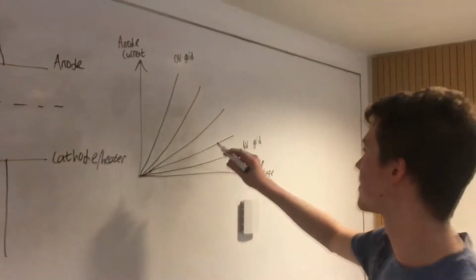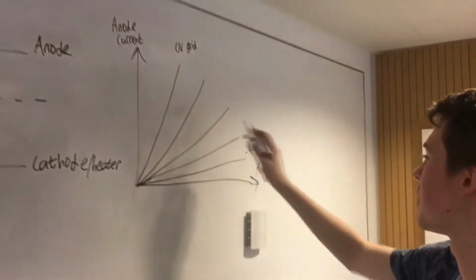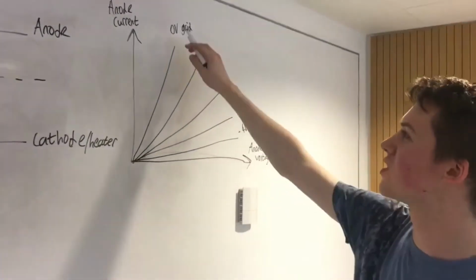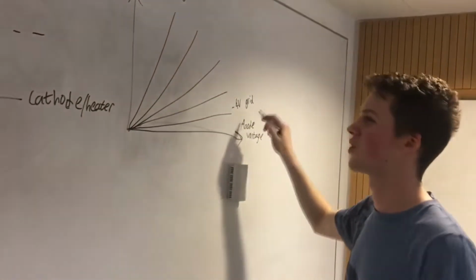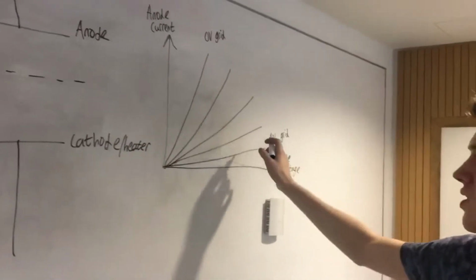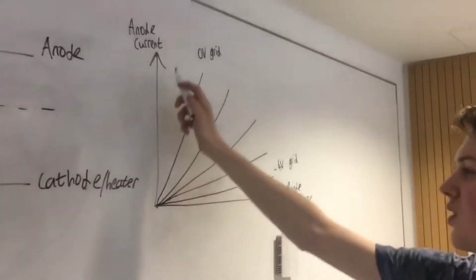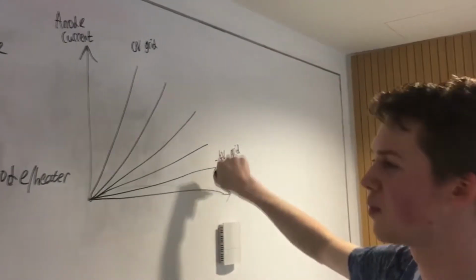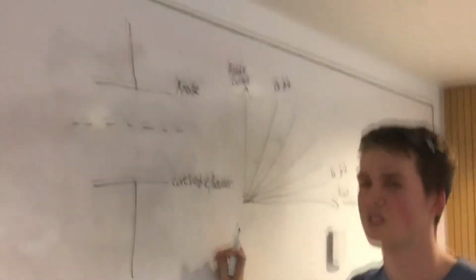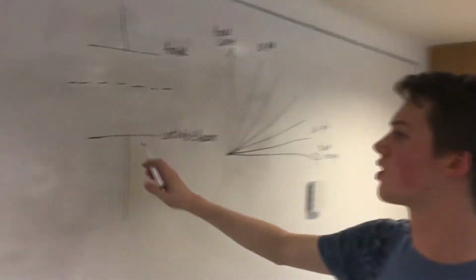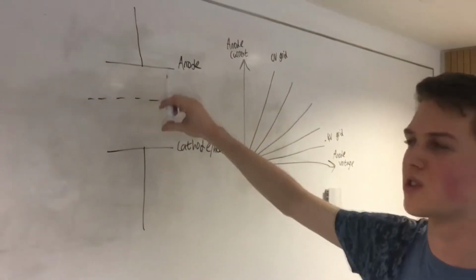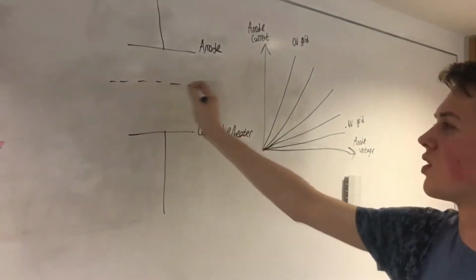So from this diagram we can see the effect on the anode current when we apply different voltages to the grid. This is starting with a 0 volt potential difference on the grid, going down to -4 volts on the grid. The cut-off bias is a term used when no current will actually flow between this, which would mean that this anode current would be 0, so it would be below -4 volts on this diagram. This can allow the triode to act as a switch, because it can completely block the current passing through the junction with just this small control grid added.